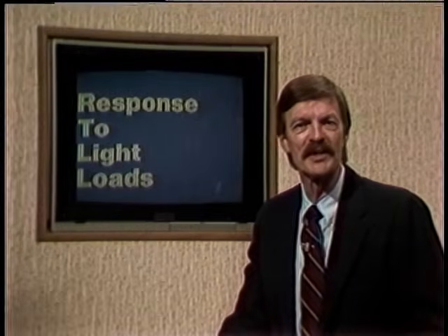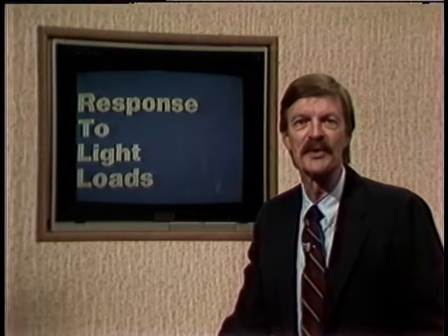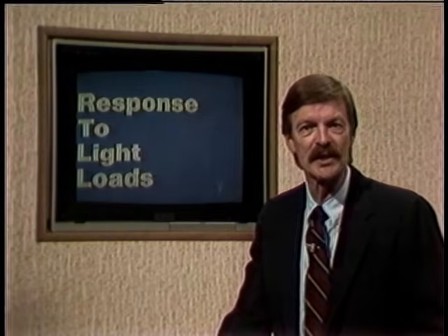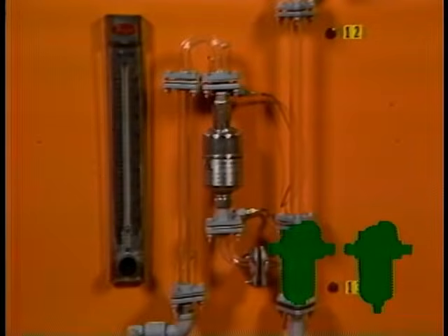Steam traps must be sized to handle the heaviest loads they might encounter. When production is down or demands on the system are low because of the season, traps may be subjected to loads far below their design limits. The trap must continue to discharge condensate as it is formed and trap live steam in the system even under these low load conditions. The IB and DC compensate for low load situations by operating in a condition known as dribbling.